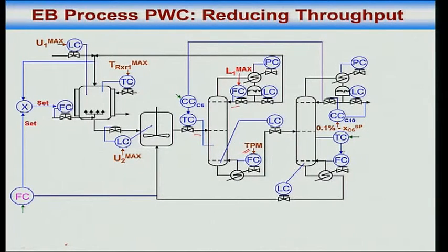In fact, whenever I can, I'll take up temperature control, and I'll take up ratio control whenever I can. I could have also controlled the stripping tray temperature by adjusting the reflux in the rectifying section. I could have done that too. It's just that this is simpler. Yeah, this is much simpler.